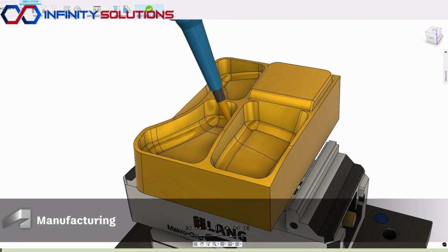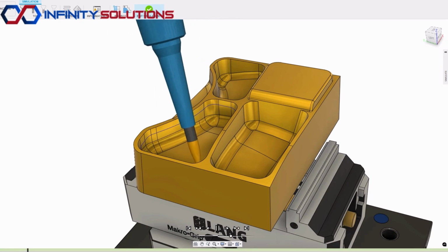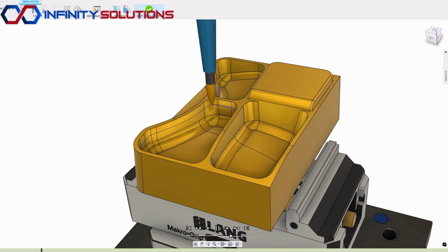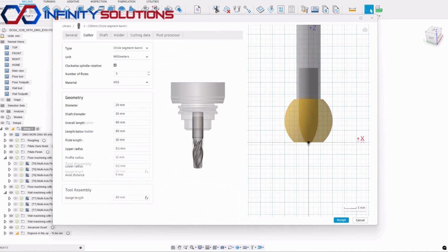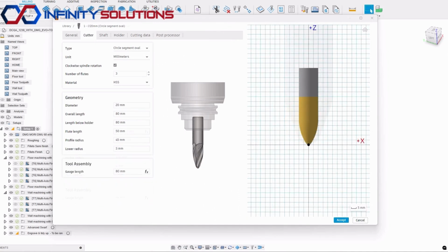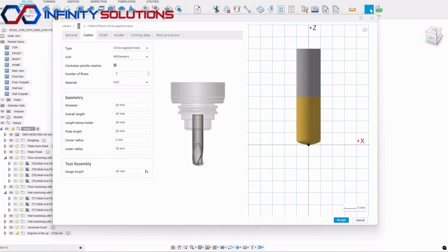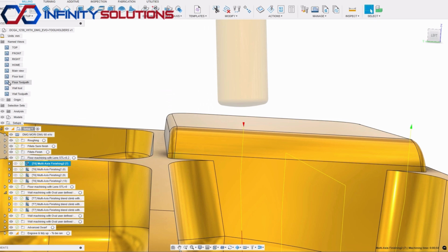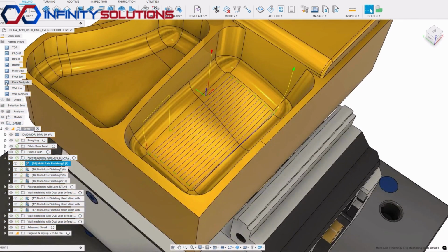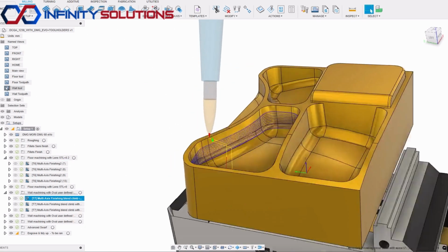A new toolpath called Multi-Axis Finishing is now available and is unique as it can utilize circle segment cutters to machine wall and floor geometries. Barrel, oval, taper, and lens tool geometries are also supported, allowing you to capitalize on their ability to use large step-overs to reduce cycle times, but still maintain the high-quality surface finish you desire. When machining floors, the toolpath uses a scallop strategy. In the case of machining walls, you have a choice of blend or scallop to meet your needs.